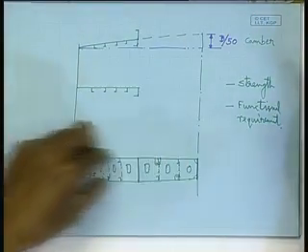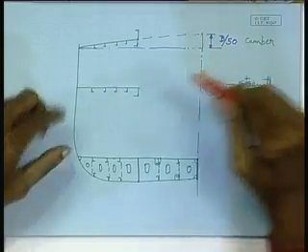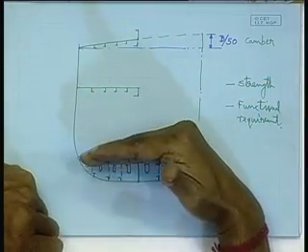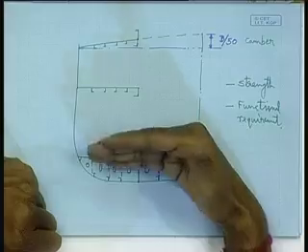So, here we get the double bottom, because for any ship you need a good flat surface for storage of cargo. So, it has to have a double bottom. That is one of the functional requirements. Another, for liquid cargo, you do not need a double bottom because liquid can go anywhere, but from the pollution control point of view, a double bottom is mandatory for an oil tanker.